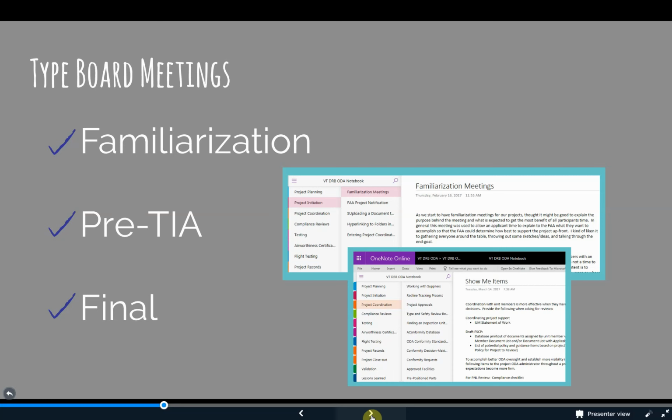Everything that can impact safety should be identified like that, or can be completed after, like a damage tolerance analysis. This is the time to see how things are shaping up. The final TCBM is required for projects that had flight testing and are again a time to provide status of the project, but more specifically, verify each technical discipline has accomplished everything needed to show compliance.